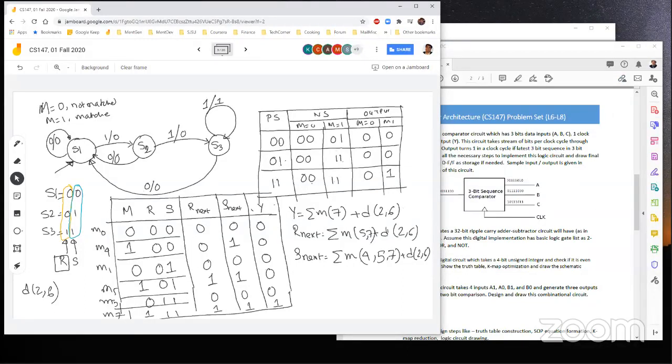Okay, now from there, you can actually have the K-map and etc. Use a D flip-flop for this, implementing this R. In the D flip-flop, this Q is really your R next, where the D is really your R. Okay, in the Boolean table.